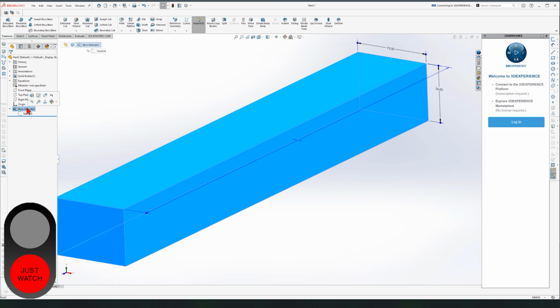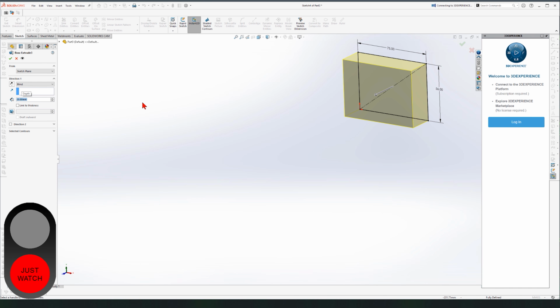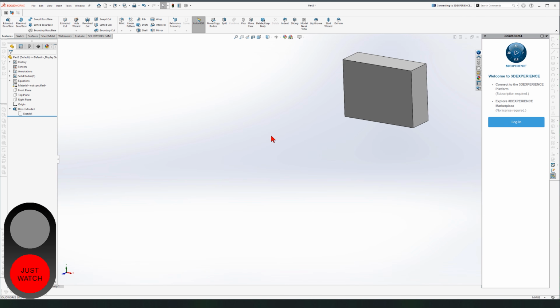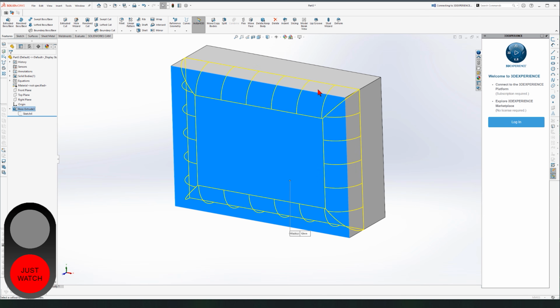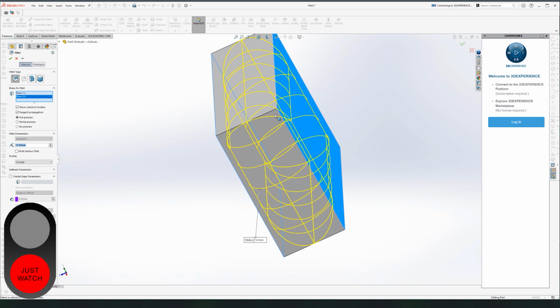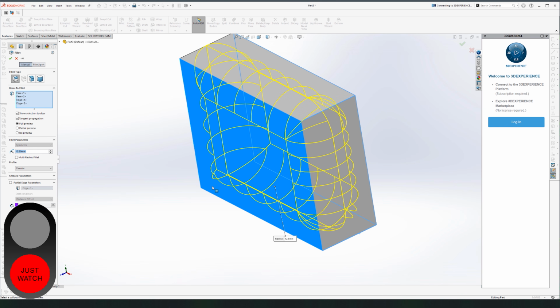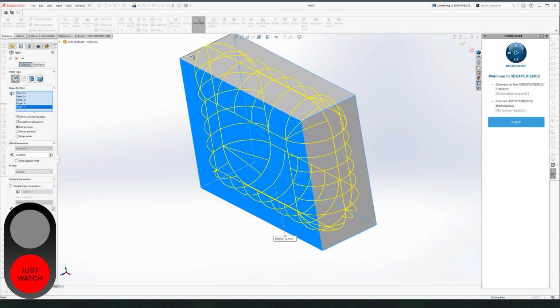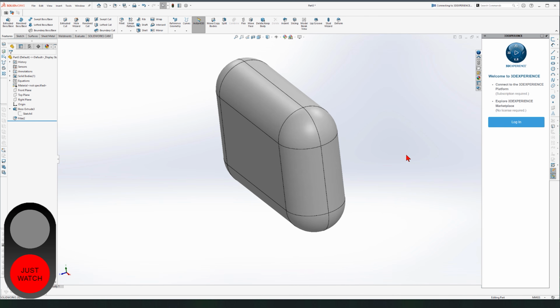Edited, and now we edit the feature, the light is red, so let's turn this into 25 and click OK. Now all these corners have to be rounded with a diameter or radius of 12.5 should be fine. Let me see. We select these 4 lines and it looks something like that, right? Fair enough.